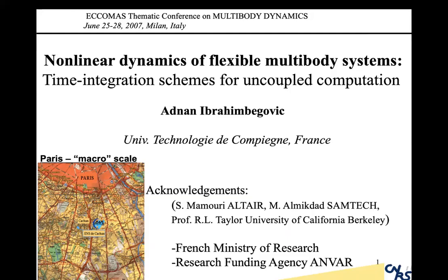Before that, they were assuming that the components of this multi-body system were rigid, and could be represented with basic modes, and all the flexibility was concentrated in the joints. Now the parts of these machines are becoming more and more slender because of very high resistance composite materials. So the deformation becomes larger, and the operating speed is also getting larger. With the operating speed and high inertial effects, deformation becomes important.